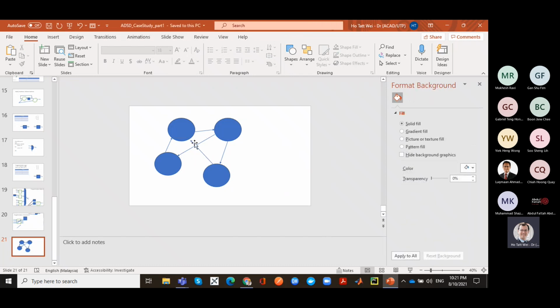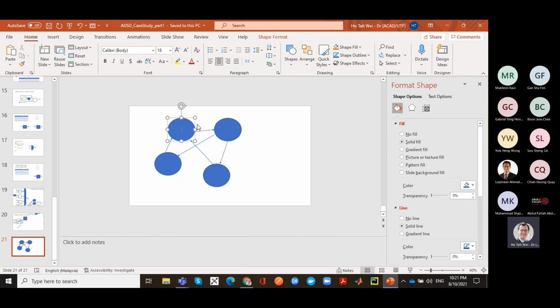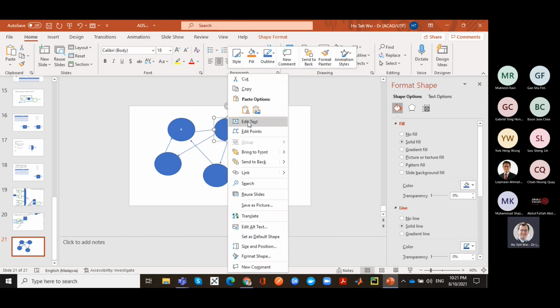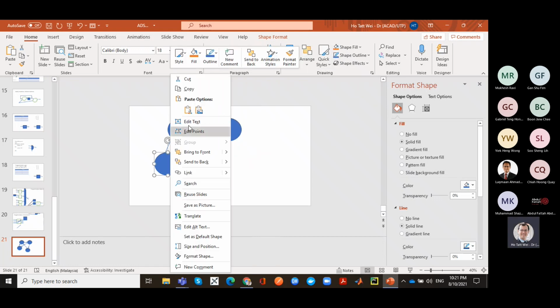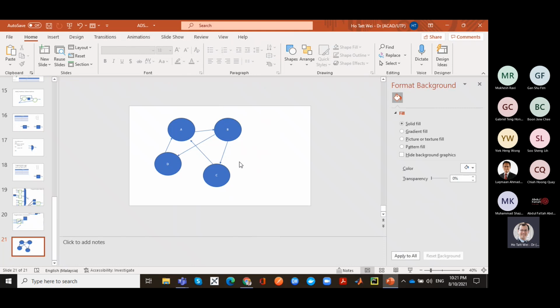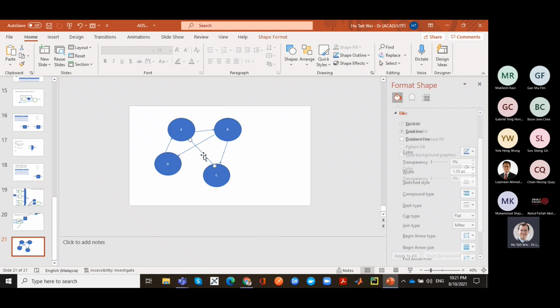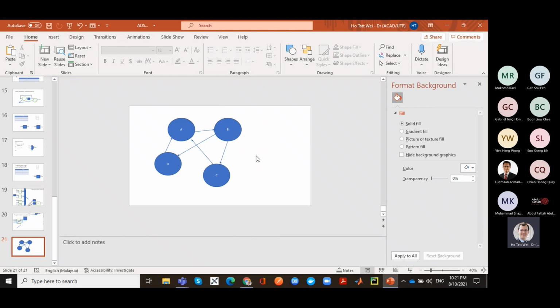If I show you a state transition diagram like this, and I just call these states A, B, C, and D. In practice, I would discourage you from calling them A, B, C, D because they're not descriptive. You should call a state, as best as possible, by the mode of operation it is doing. For example, each state could be an instruction in the microprocessor, like add, load from memory, subtract, shift left or shift right, or divide. But for simplicity, I'll just call them A, B, C, D.